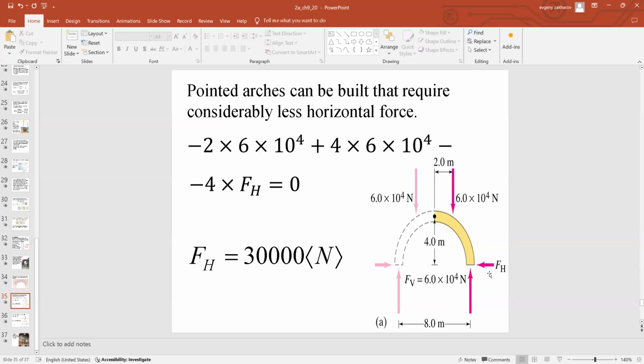And then the horizontal force that is unknown, we want to withstand that force so that the whole cathedral stays stable. Say this is your wind that blows in that certain direction, and you want the arc to withstand that wind. So that's the line of action, that's the axis of rotation, that's the shortest distance, so 4. So the unknown force times the 4 being the moment arm, and what kind of rotation from this force?